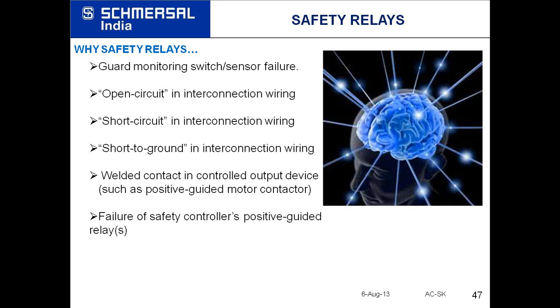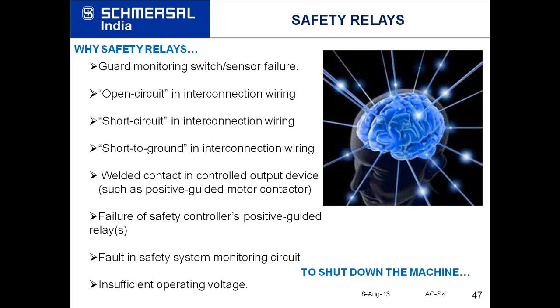Then it also checks failure of safety controllers. So it has internal diagnostics also. When the relay itself fails, it tells that it has failed, and it puts the system into a fail-safe mode. So these are the parameters which a safety relay takes care of.